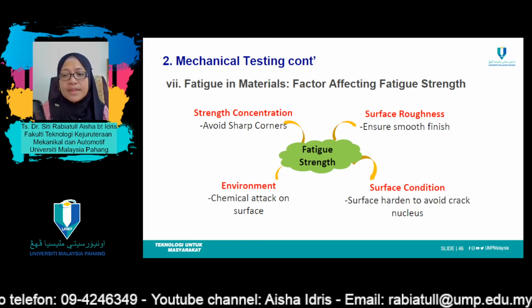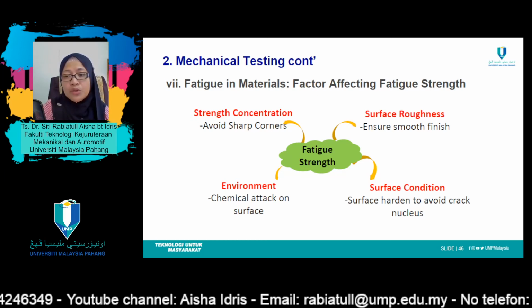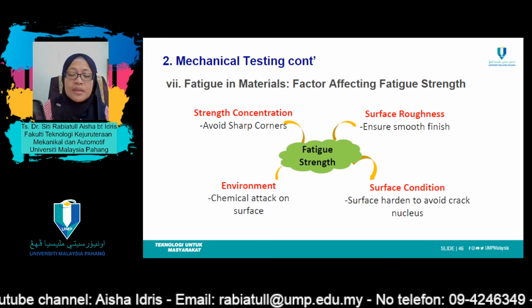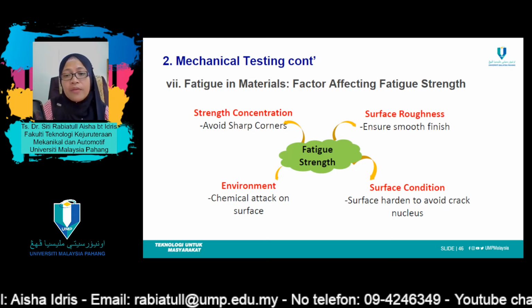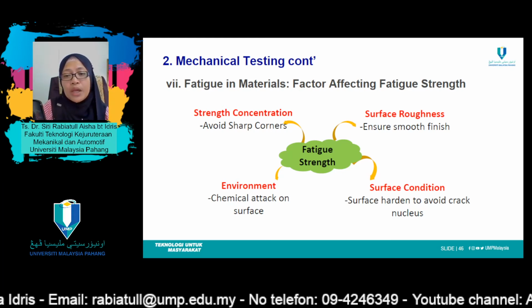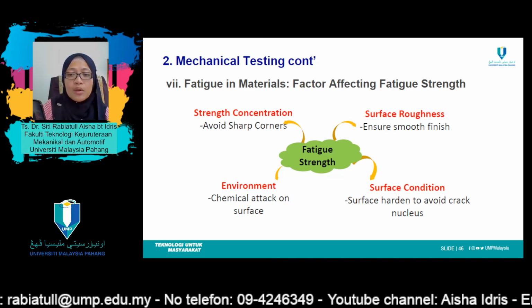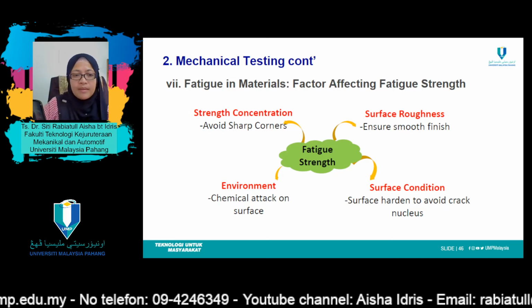After that, surface condition. The surface itself needs to be hardened to avoid crack nucleation. So this is additional work for surface condition. After that, environment. Normally, chemical attack on the surface actually leads to low fatigue strength.